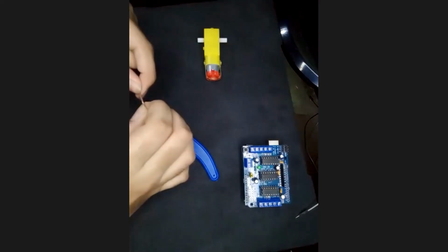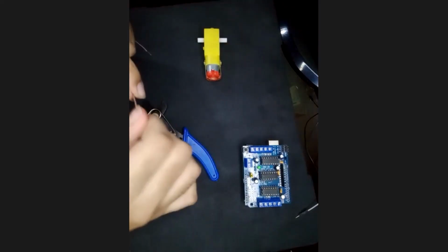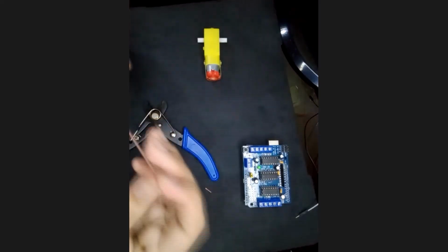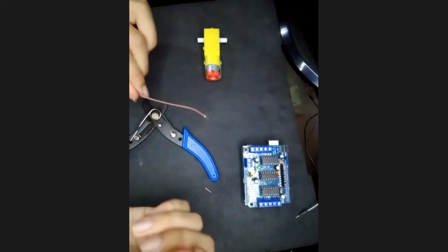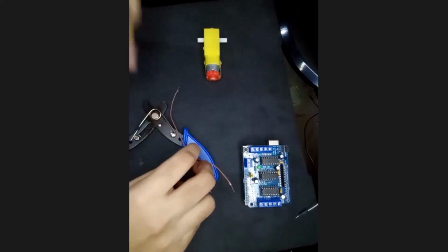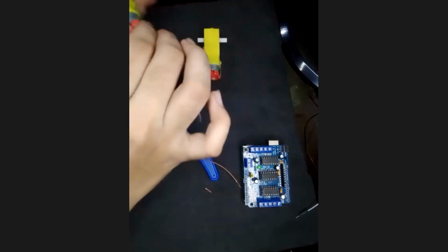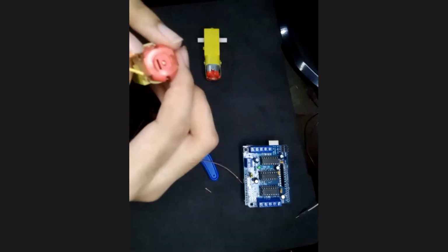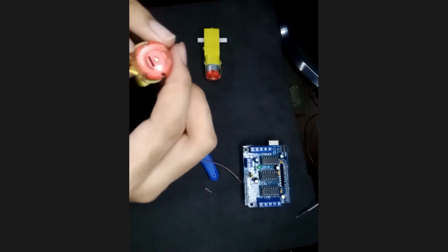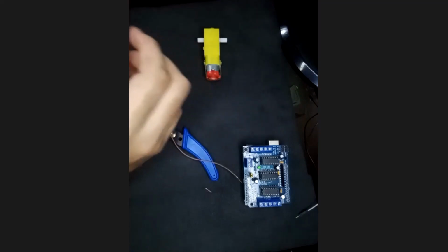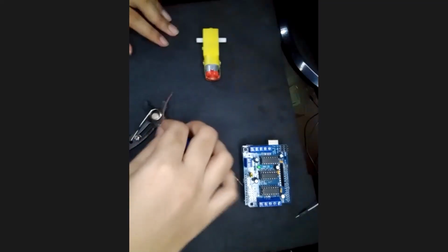That sounds good. Yeah, and the wire should just come out pointed like this, which actually makes it easier to solder, because if you just pull it out, it will have frizzes at the end. So it makes it really difficult to solder it on. Like these ones, I didn't twist them out, and you can see that they're frizzed at the end, which just led to this horrible solder. Okay, so just don't make this mistake that I did.